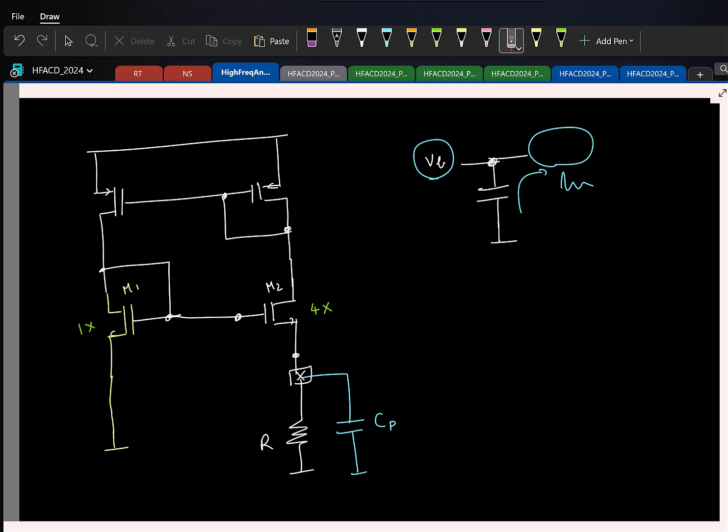That's because the moment you put a capacitor, it gets charged to VB, so it is now acting like a voltage source, right? So this is typically done on chip for making sure all DC potentials remain fairly constant. Otherwise there can be some stray coupling from somewhere that can momentarily change, reduce or increase it. So to keep it fairly constant, this is something that is done.